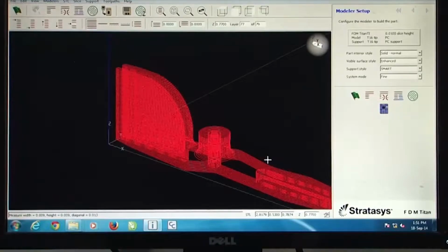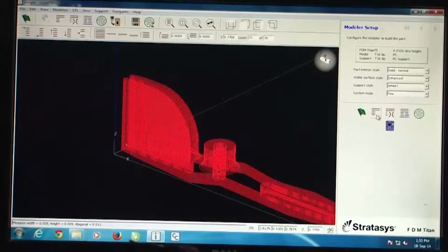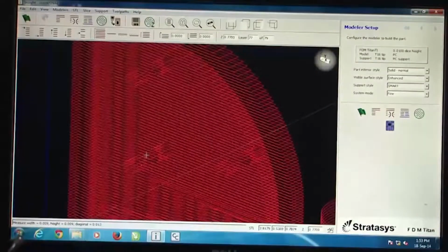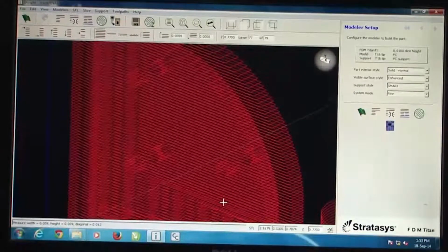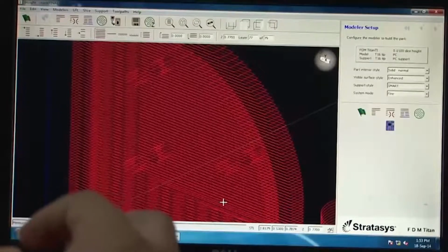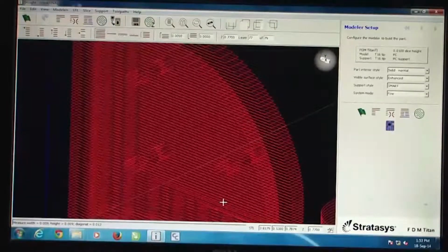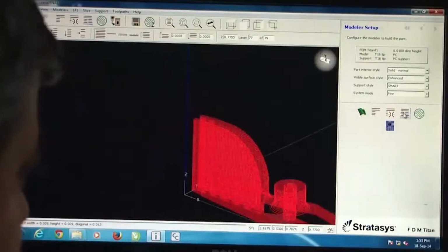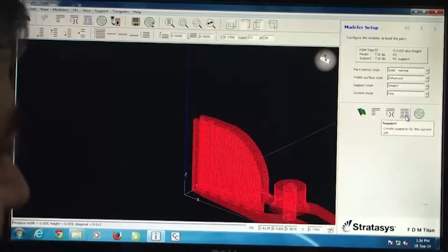So once the slice plot is done, the question of defining the tool path comes into picture. So the other option now we have, once we have done the slicing, is to create a support system here. There are certain holes, etc., which you are not able to see because of the intense slicing, but you can see there are certain holes which have to be created. Okay, and therefore there has to be a support within them, where typically the density would vary, and there can be easy cleavage, so that the support can be later taken off to create that hole in that particular dense structure. So having said that, let us go to this other option here which says support.